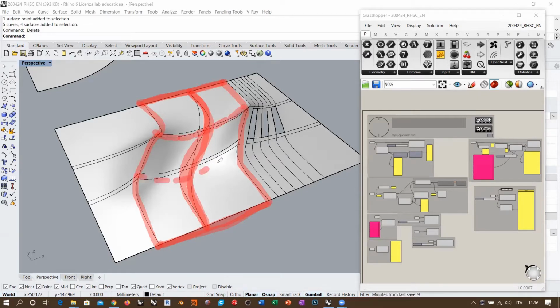So we will also need at least one cross section, probably in the mid section of these curves, like this. But we are going to deal with 1, 2, and 3 curves in this direction, and with 1, 2, and 3 curves in the opposite direction, which leads us eventually to the only possible, well, it's not the only possible command, but we can work only with network surfaces right here.